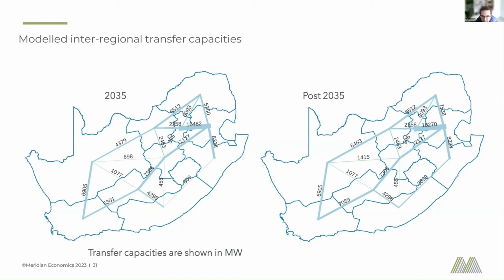It's not saying that there isn't a role for pumped hydro. I think one of the challenges pumped hydro is facing is that it's great from a dispatch point of view if you have long duration storage and you can capture, especially, moving wind patterns, for example weather patterns, and store it for the shift from one day to the next. But part of the problem is that to actually charge the storage, your long duration storage bites you on the charging side because you can only charge it at a very low rate.